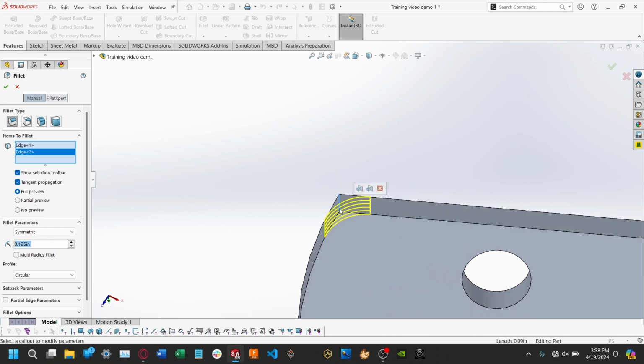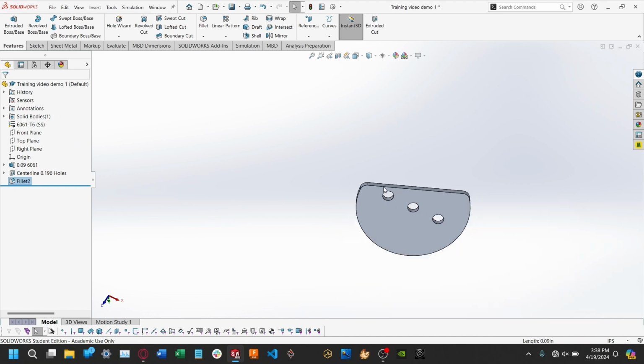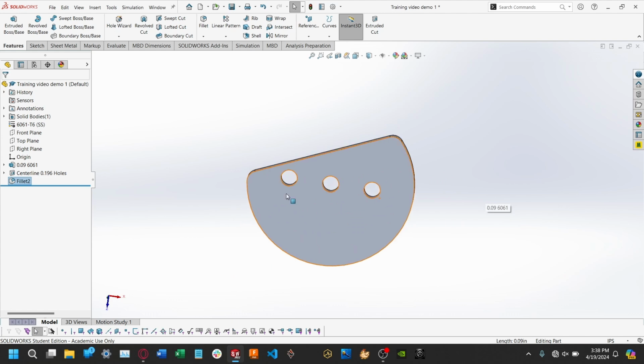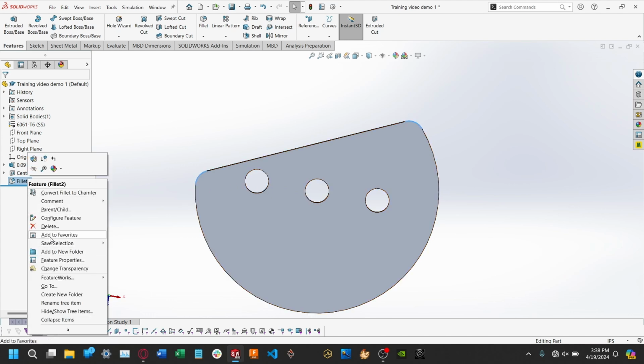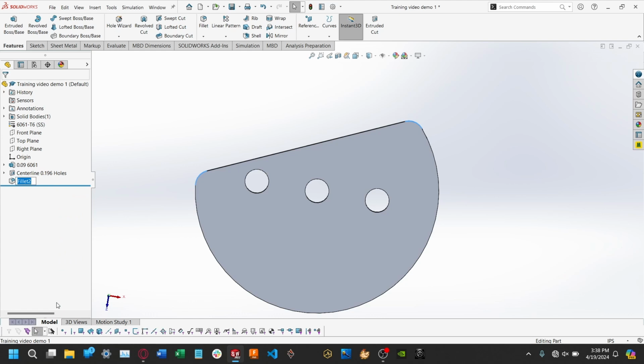Now, the most basic of these, and the one that requires absolutely no sketches to run, of course, it requires a part that has to have been sketched, but it doesn't run off of any sketches or sketch parts or anything, is the fillet. What a fillet means is that we round the corner of a part. We use this most of the time. Whenever we have a sharp edge, we will typically use a fillet. We will definitely have to use a fillet if we have an interior sharp edge.